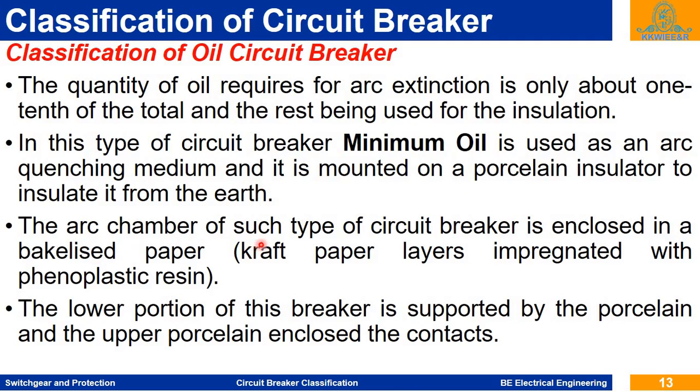The arc chamber of such a circuit breaker is enclosed in bakelized paper. Bakelized paper means layers of kraft paper impregnated with phenoplastic resin, so that the insulation level of the bakelized paper is increased, and it also supports the porcelain insulator.